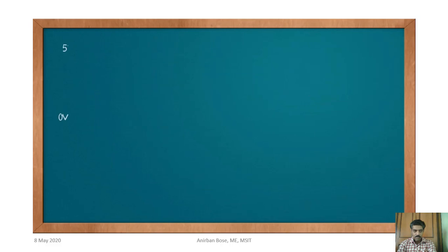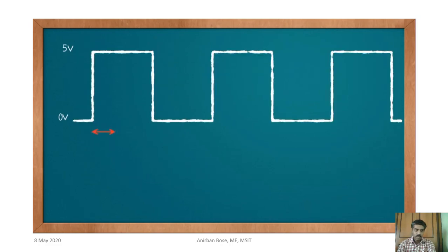Let's imagine a PWM signal that oscillates between 0 and 5 volts. Let's say this signal has a duty cycle of 50%. Something interesting will happen to the output voltage. Instead of being 5 volts as expected, it will now be 2.5 volts. Simply putting it, this is because in a PWM signal you multiply the max voltage by the duty cycle. This is the formula. By applying this to our situation, you will see we reach 2.5 volts.